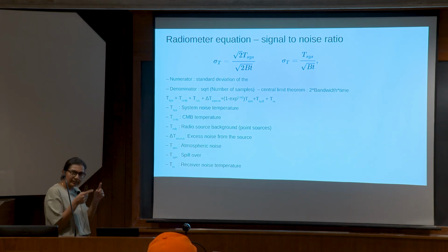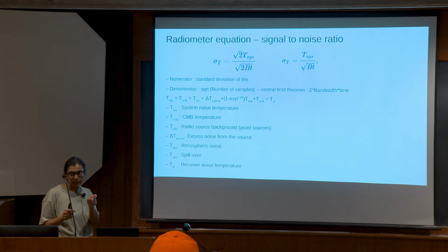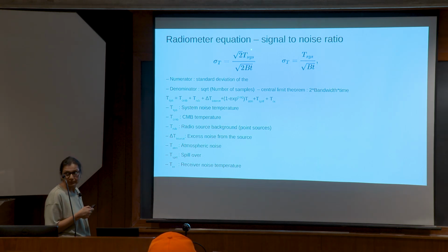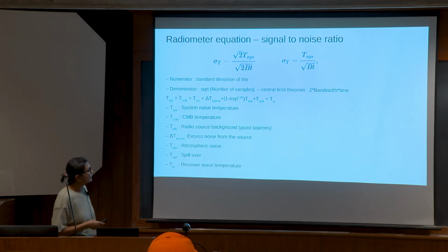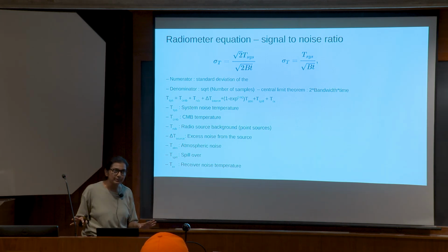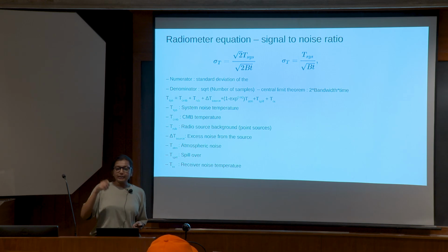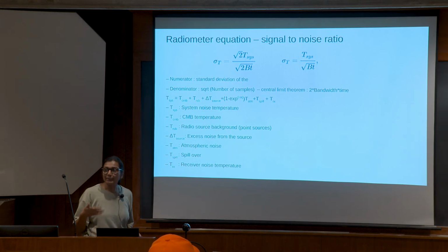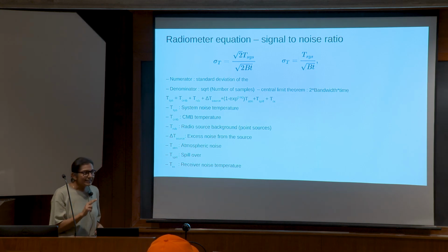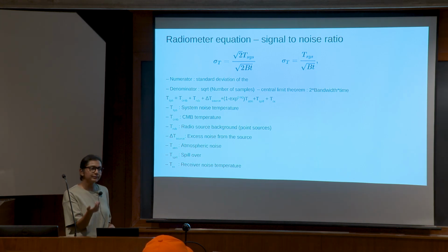When you take the sigma of the power, not the voltage, you get the square root term. Okay, there's a square root in this thesis. In the denominator, effectively, is just the number of samples. If I am collecting data from a receiver, from a telescope, there is something called the Shannon-Nyquist sampling theorem, which tells you have to sample the signal at least 2 times the bandwidth or the highest frequency.